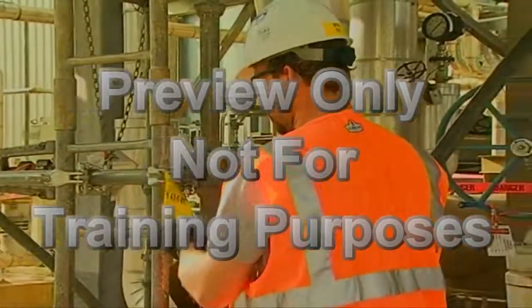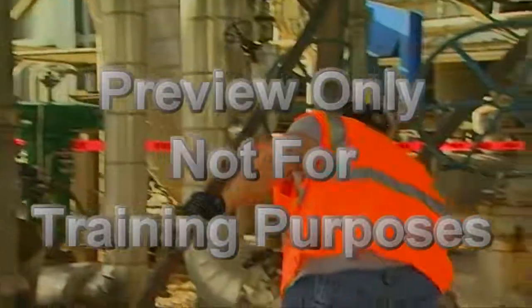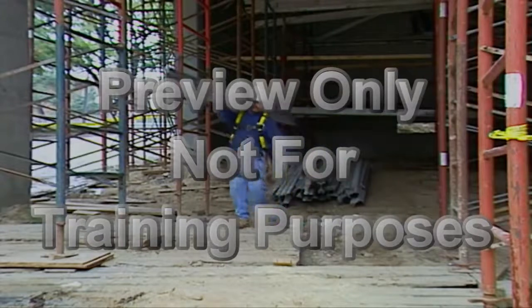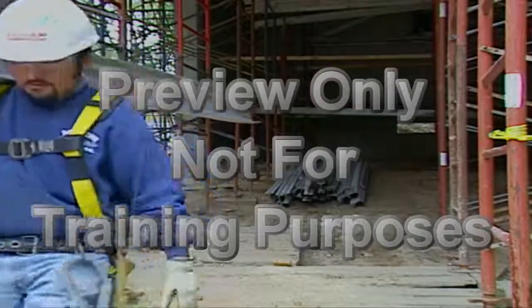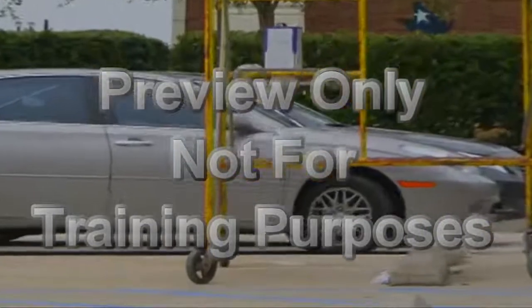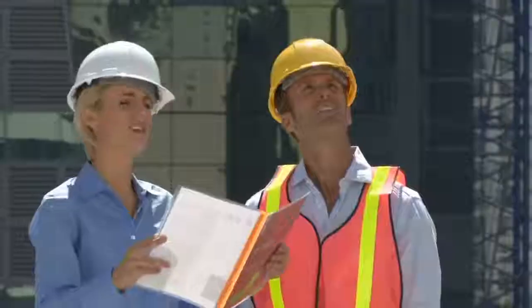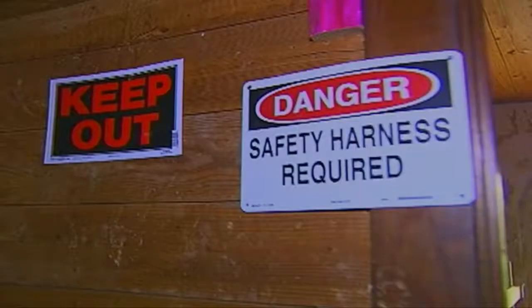Scaffolds must be inspected for visible defects before each shift by a competent person and after any event that could affect a scaffold's integrity. Any part of a scaffold that has been damaged or weakened must be repaired, replaced, braced, or removed from service so that OSHA strength requirements are met. Scaffolds cannot be moved horizontally while workers are on them unless specifically designed for such purpose. Workers should not work on or from a scaffold during storms or strong winds, unless it is determined to be safe by the competent person and the workers are protected by either personal fall arrest systems or wind screens.